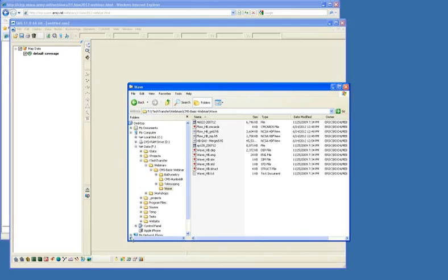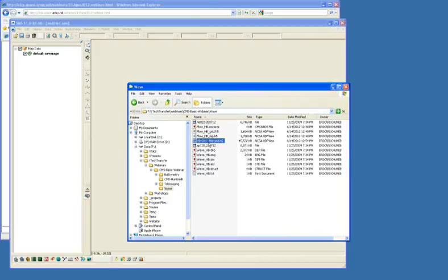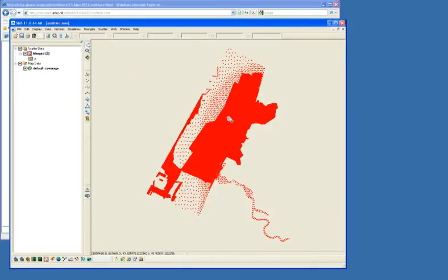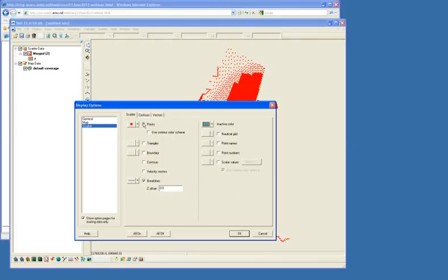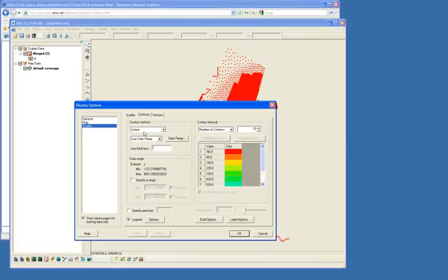So looking in that wave folder, I'm going to grab our merged bathymetry that we've used a couple times. I've actually modified it a little bit and taken away some of the extra points that we don't really need. I've got it a lot closer down to the area that we're interested in. So I'm going to turn on looking at the contours so I can actually see the bay.